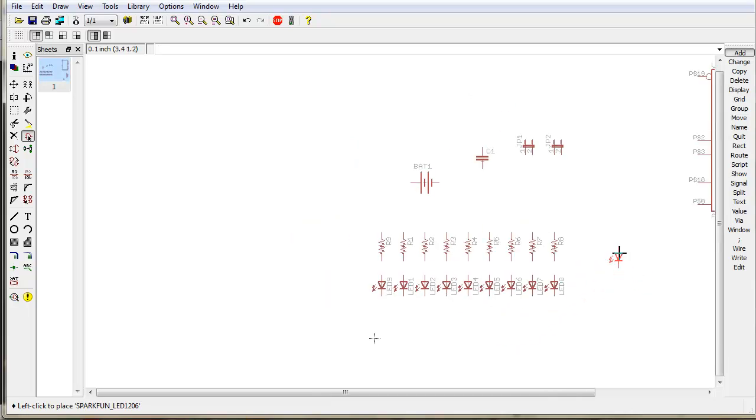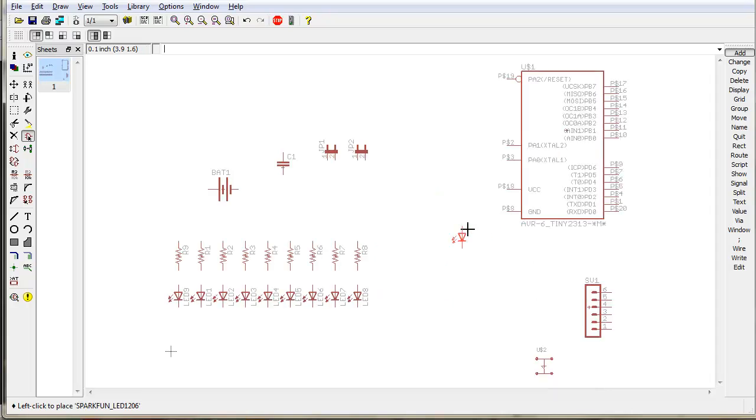Okay, so we've added, I'm going to hit Alt F2 here on the PC. That's going to do a zoom to fit all of the parts that are currently on layout. So we are almost there. Let's use another one of the commands called move, which basically allows us to pick up parts and move them around a little bit, make things a little bit neater. I usually like to add most of the components first before adding any of the wires.